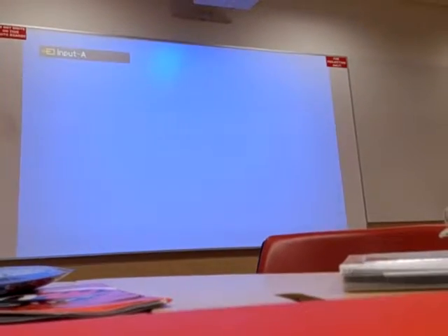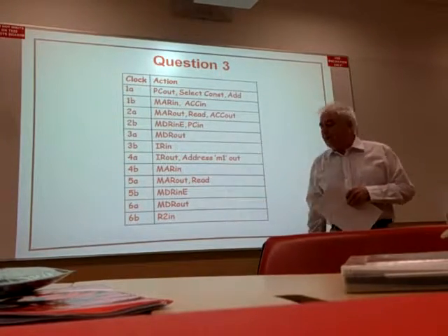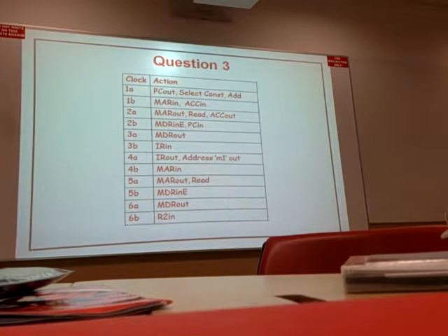No need to use the ALU because there is no operation. But you have to use the register to store back into R2. So it's 6. It's not quite so simple, but let's go through it in detail. You just say 4, I say 2 more, 4 plus 2 is 6. Okay, you get the idea.